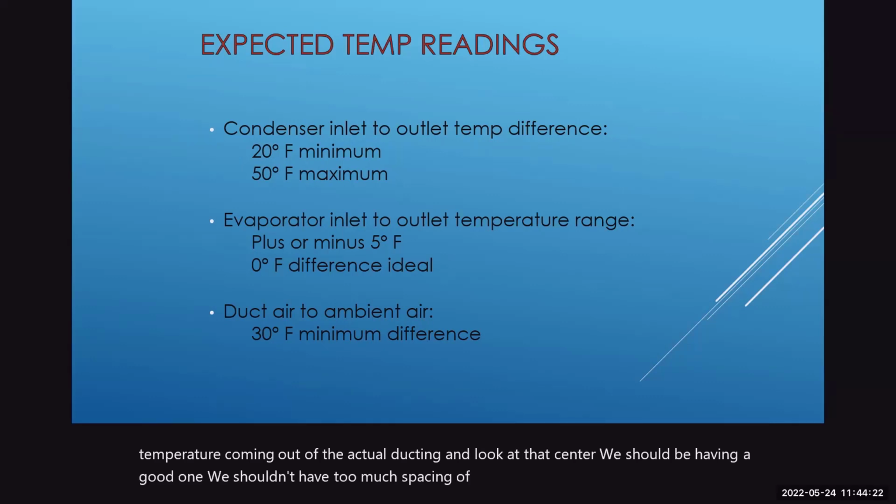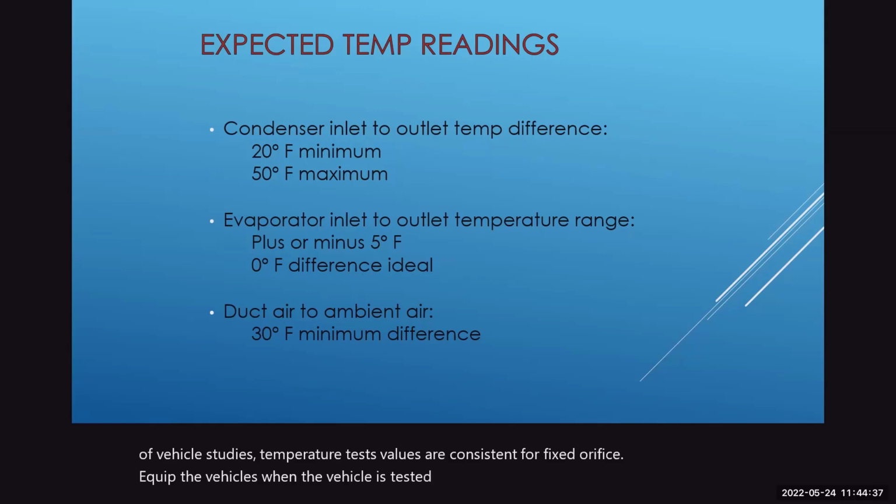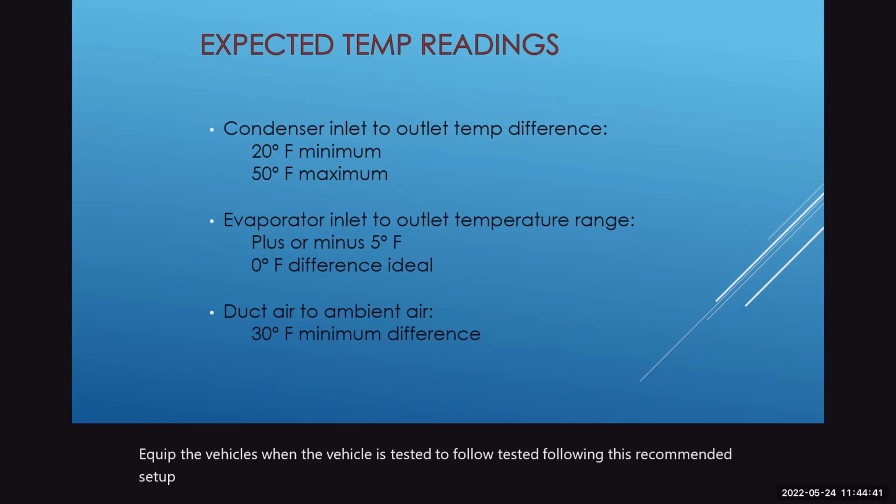Okay. And so based on multiple vehicle studies, temperature test values are consistent for fixed orifice equipped vehicles when the vehicle is tested following this recommended setup. When performing temperature testing on expansion valve equipped vehicles, evaporator inlet and outlet tests are not performed.